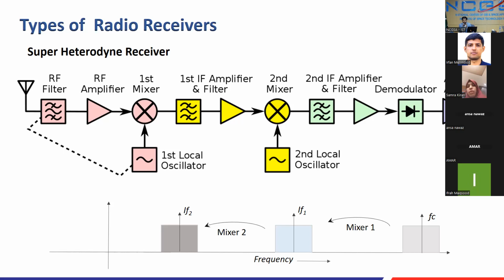There are two separate systems. One is an IFM, measuring the frequency of the incoming signal. Then there is another that extracts the information of video out, the information in the amplitude. Then there's a third system, closely placed, that extracts the information of phase. But the first two systems, the IFM and the video out signal, bring the pilot to the scope. Those two parameters are directly fed to a system that compares them to a library, and on the pilot screen it says first that it is a threat, okay, from this quadrant.